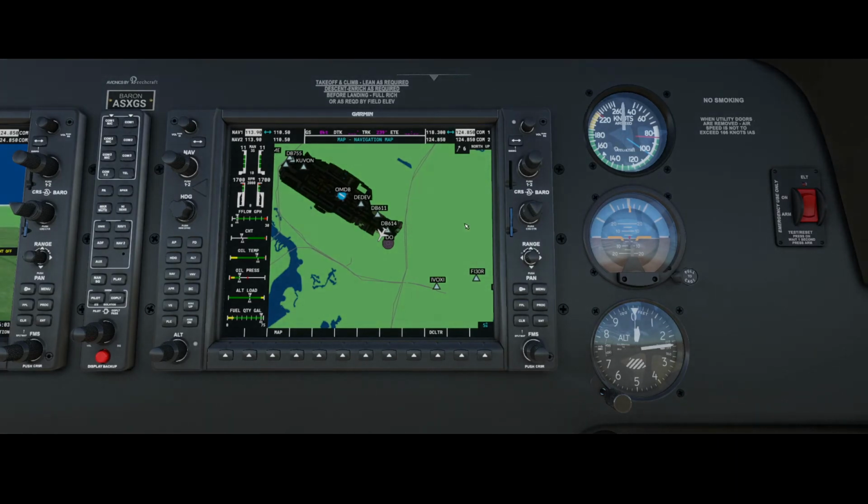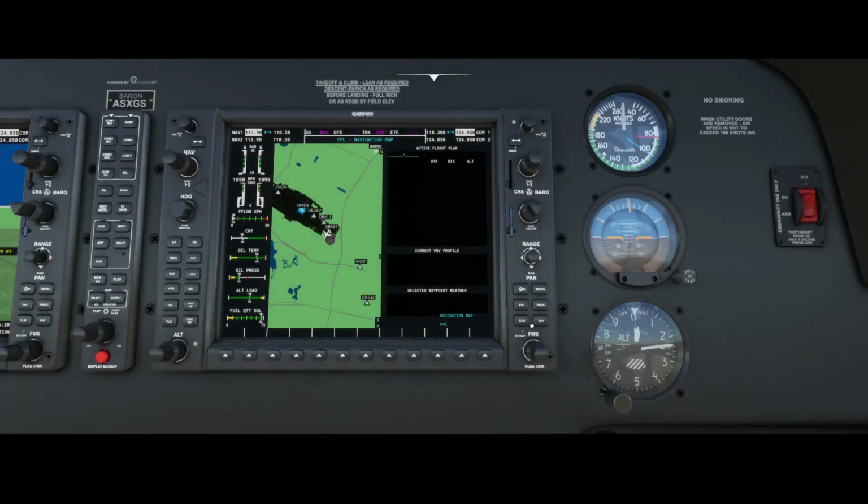For those who've watched the Cessna how-to, those will recognize these two systems, right? Because they're identical. There are more airplanes in Flight Simulator which have this interface. So if you already are familiar with that, then it's good. So let's switch on the engine a bit lower to 1000 RPM, and let's start planning our flight. So what we're gonna do is we're gonna press the FPL button, and then we're gonna add OMDB as the starting point. That's always what you need to do, right?